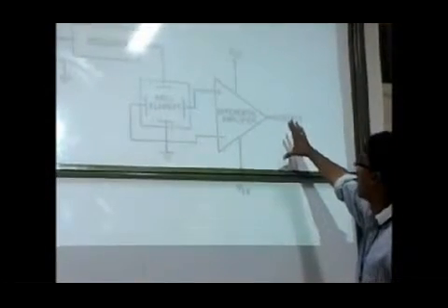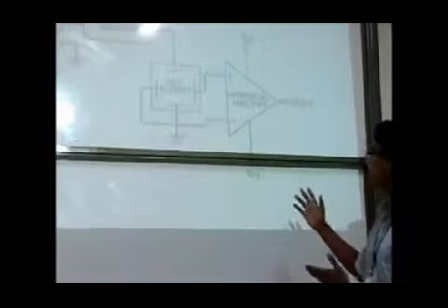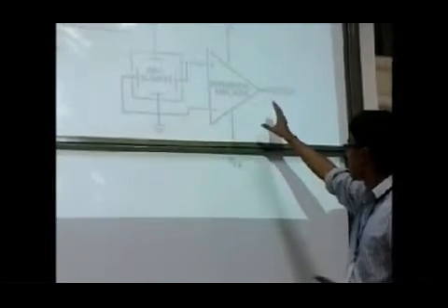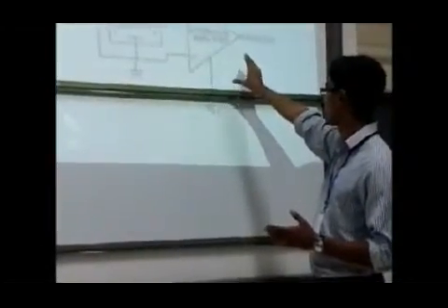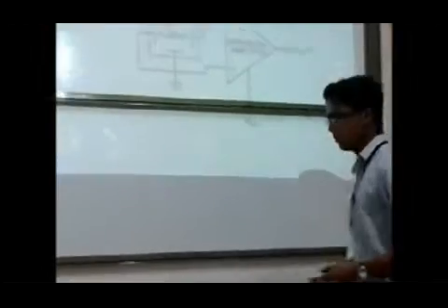If you take the voltage with respect to this terminal and the ground, then the voltage measured will be the common mode voltage. It's always present there. So if some other amplifier is used, it will amplify the common mode voltage. Our aim is actually to amplify the potential difference only. So if you use a differential amplifier, it will only amplify the potential difference. So that's what we want to do. That is the function of an analog Hall effect sensor.